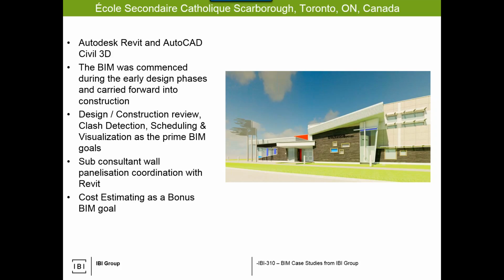And that's always the thing that I want to qualify with clash detection. It's an admirable BIM goal to say we're going to clash detect on our model, but it takes some diligence to step back and define what needs to be clashed. So is it systems against the building? Are you clashing building against building? Do you want to know if ductwork is going to specifically interact with major structural components? Having that definition enriches your clash detection. So it's not just you press the button and you get those 15,000, 20,000 clashes and you shrug your shoulders and say, well, what was really the point of all of this, right?